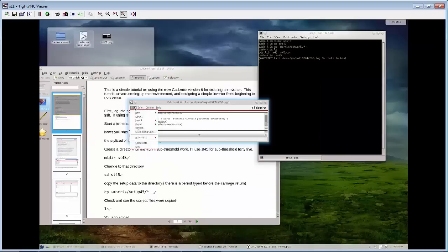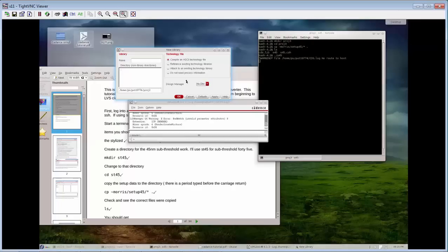So as you are doing it for the first time, go to file and then new, and then create a library wherein you can save all your project files if you do anything further. So name the folder like E224. Attach this library which you're going to create to the previously existing library in the Cadence, which includes all the voltage sources, current sources, everything. So attach it to the existing technology library and then click OK.